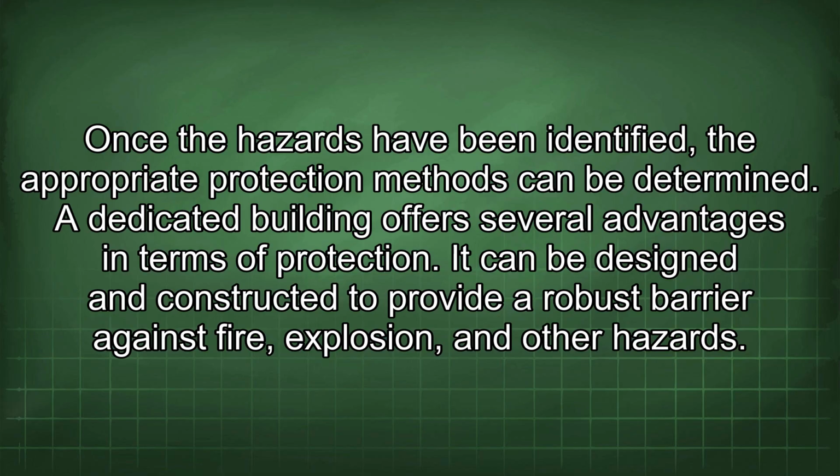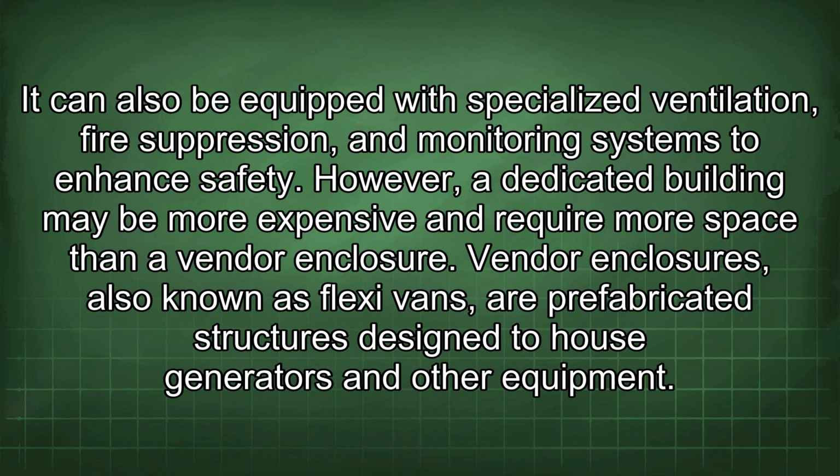A dedicated building offers several advantages in terms of protection. It can be designed and constructed to provide a robust barrier against fire, explosion, and other hazards. It can also be equipped with specialized ventilation, fire suppression, and monitoring systems to enhance safety. However, a dedicated building may be more expensive and require more space than a vendor enclosure.